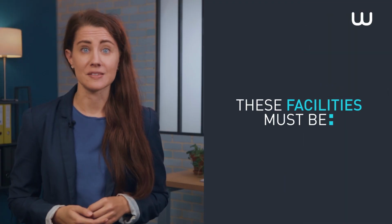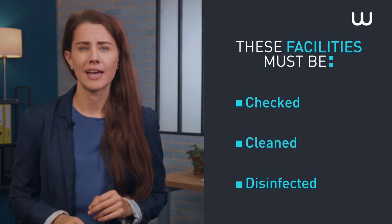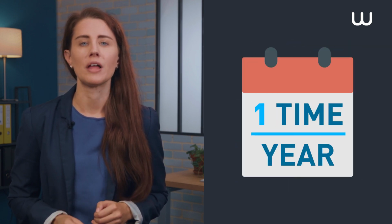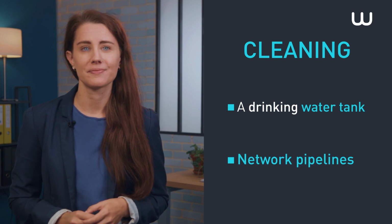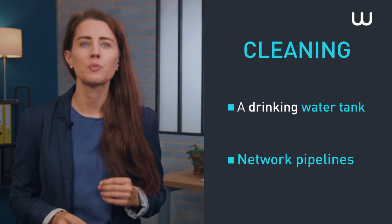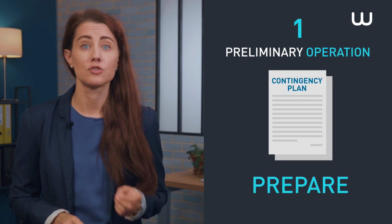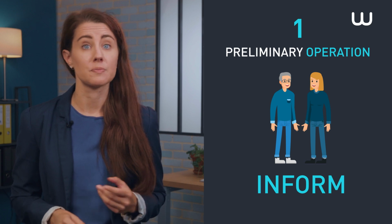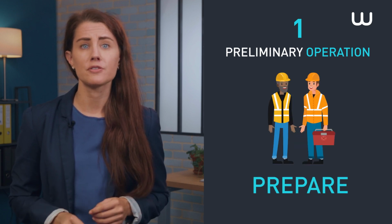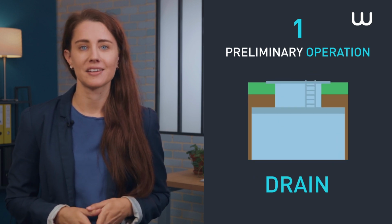All of these facilities must be checked, cleaned, and disinfected as often as necessary, and on average, at least once per year. So let's now look at the stages of cleaning a drinking water tank and network pipelines. Tank maintenance begins with preliminary operations. Prepare a contingency plan in order to maintain supply to customers. Inform users in case of planned supply interruption. Prepare personnel and the structure concerned. And lastly, drain the tank.